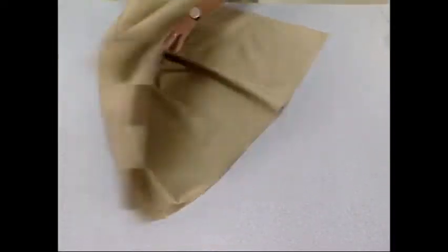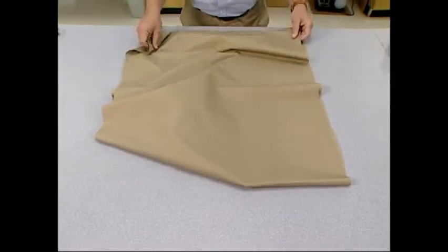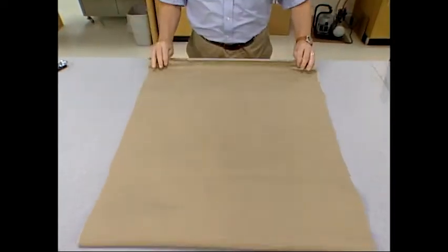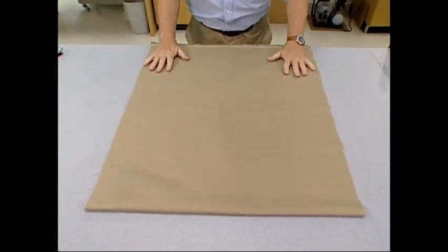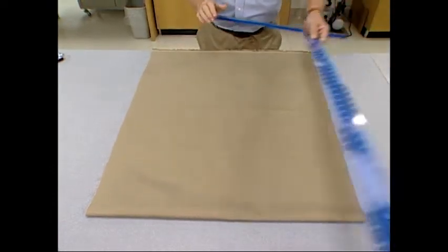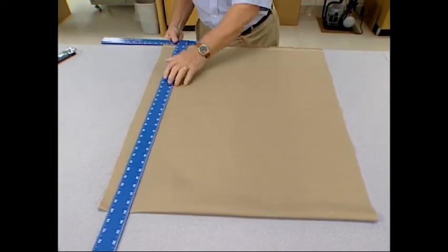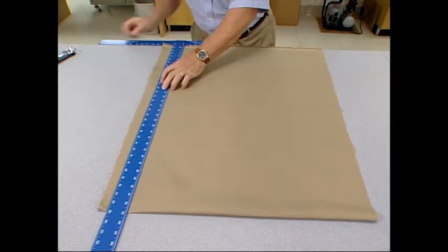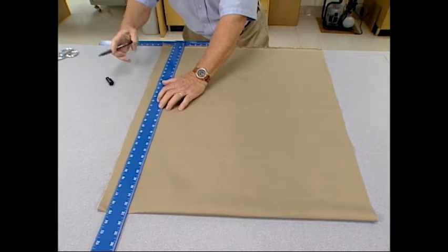Another option, B, makes use of a full-width specimen. This procedure is applicable to a full-width sample cut from a full piece, roll, bolt, or cut. Unless otherwise specified, these results will include selvages and will be on the basis of conditioned fabric. Option B is not recommended for the acceptance testing of commercial shipments, since Option A is regularly used for that purpose.